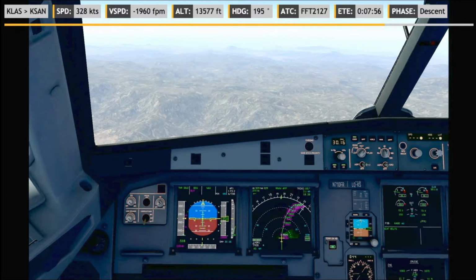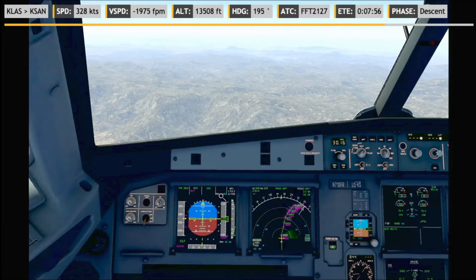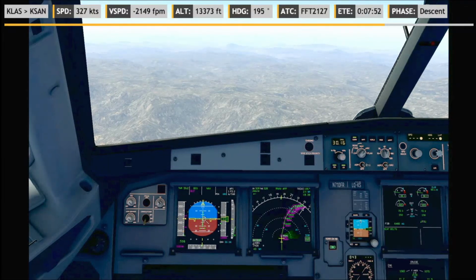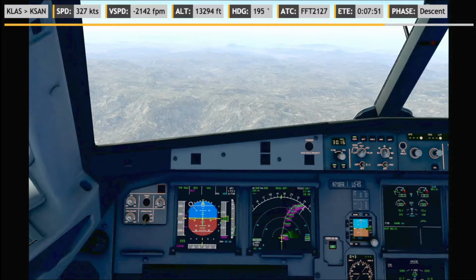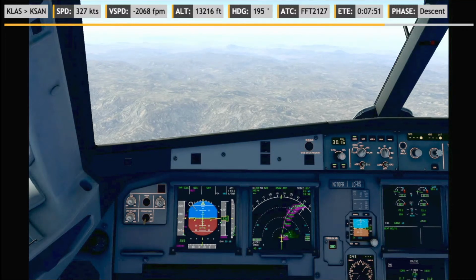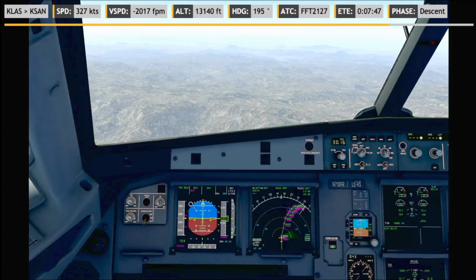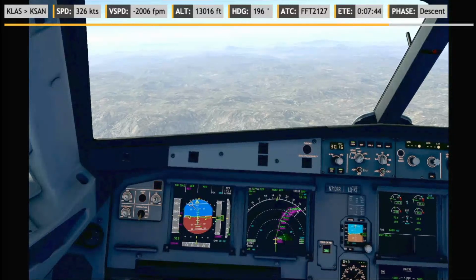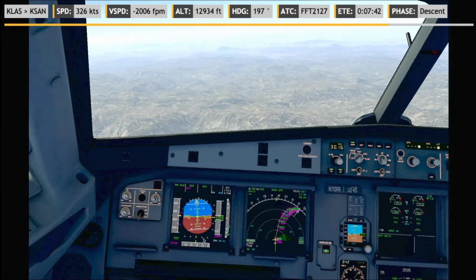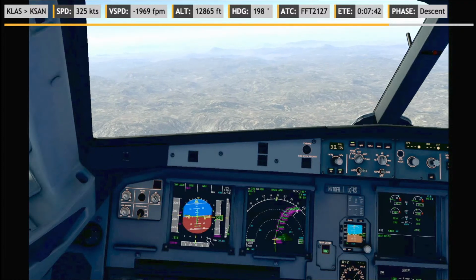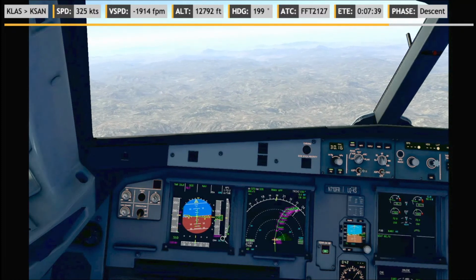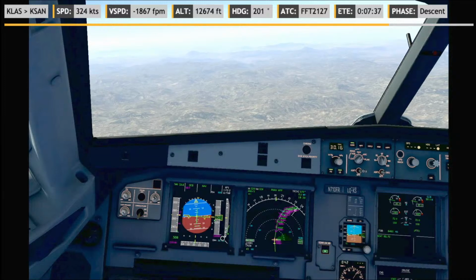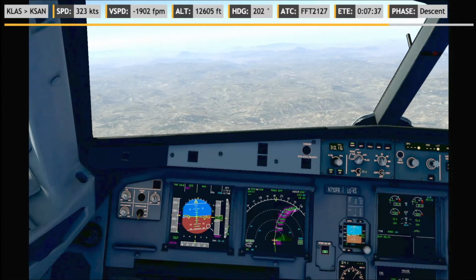Alright, 13.5, so we are within our window of altitude restrictions at 270 knots exactly. So we can pass Trixie. Next waypoint is Husker without any restrictions. It should be just 8,700 or above. Okay, so we can't descend below 8,700, which is gonna be the next thing here. There is a restriction, so well, I misspoke a little. There, 8,700.